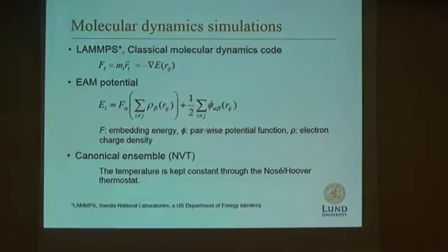To solve the system, we have used molecular dynamics simulations. We have used the freeware called LAMMPS. From this we can calculate the force on the atoms as the gradient of the potential energy. Then we get the acceleration of the atoms. We can time integrate and get the velocities and positions. And to do this we have used the EAM potential.